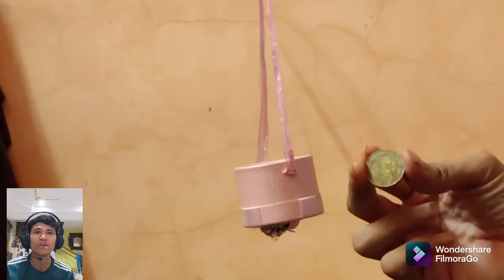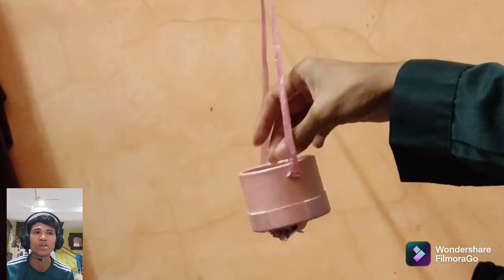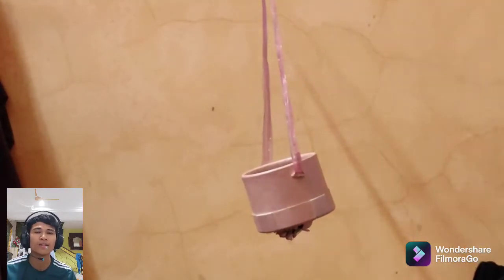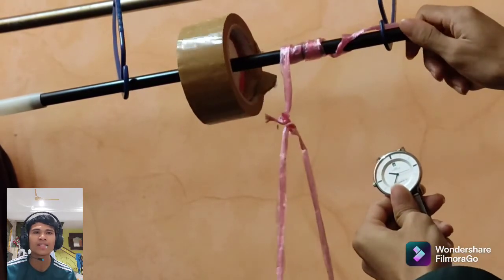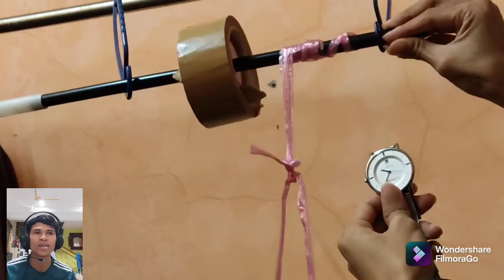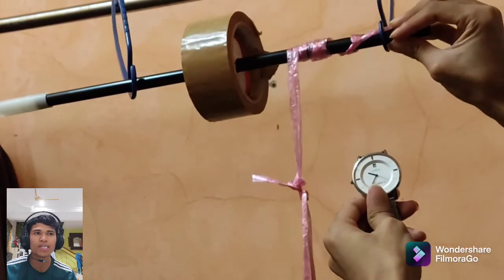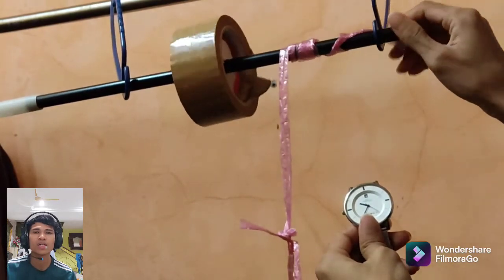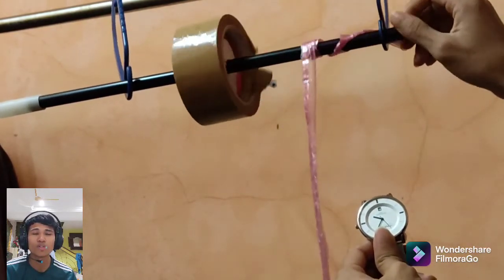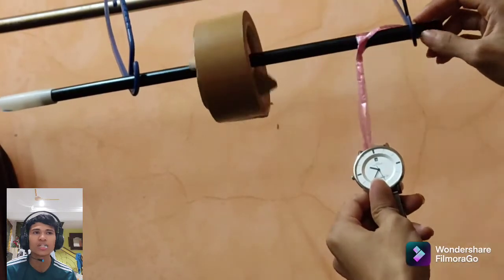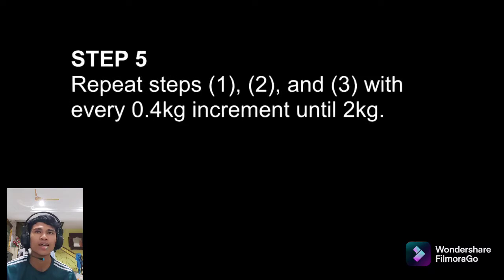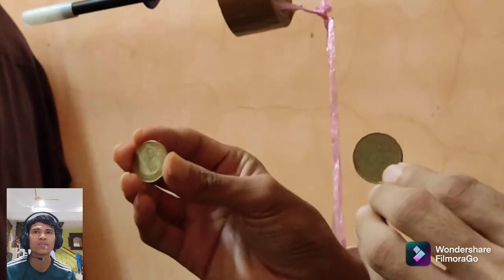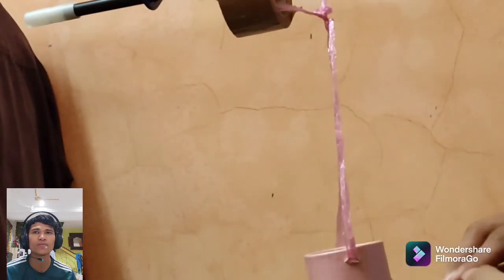Plot a graph of moments against corresponding values of angular accelerations and determine the slope of a best straight line representing the plotted points, and find the experimental moment of inertia. Calculate the theoretical moment of inertia of the disc and the axle, given the density of the disc and axle.